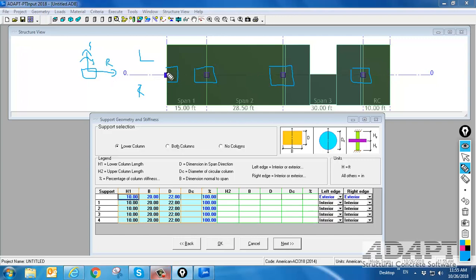We know that if we're bending about S in this direction, this is actually an end condition. So this is end, and if it's an end condition, then it's a 3-sided critical section. We have some centroid for this critical shape, which is not at the column, it's somewhere here to the right of the column. At this one, we know that this is interior, right?